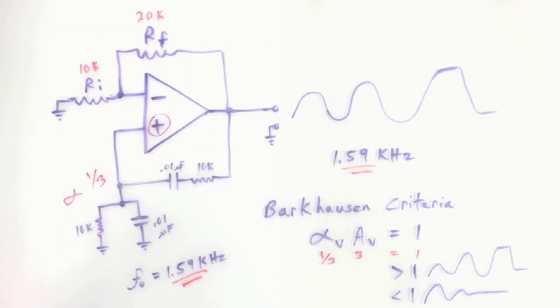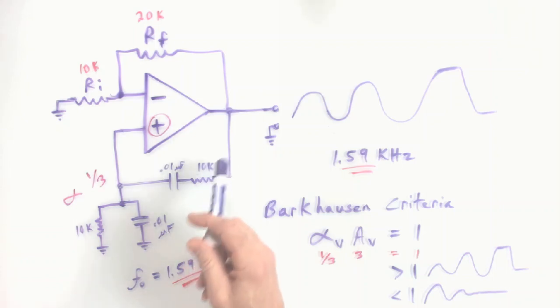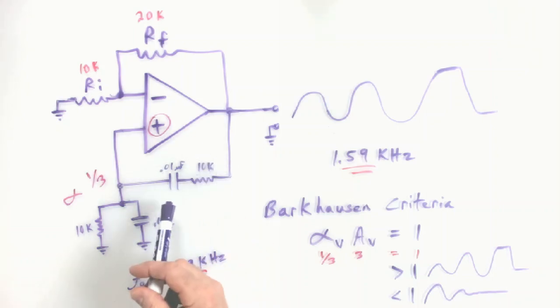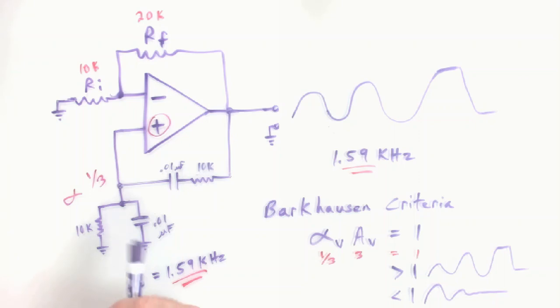So it's a little bit of a tricky business. With this particular example of a feedback oscillator, you do have a pretty easy time creating the bandpass network, I think. But then this Barkhausen criteria is no joke. It's not that easy to hit it right on 1, and you'll find that experimentally. Even though it's a simple concept, it's one of the challenges of a feedback oscillator because, like we say, there's no margin for error.